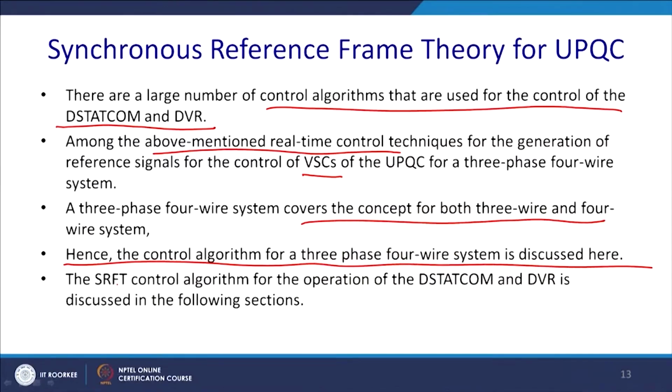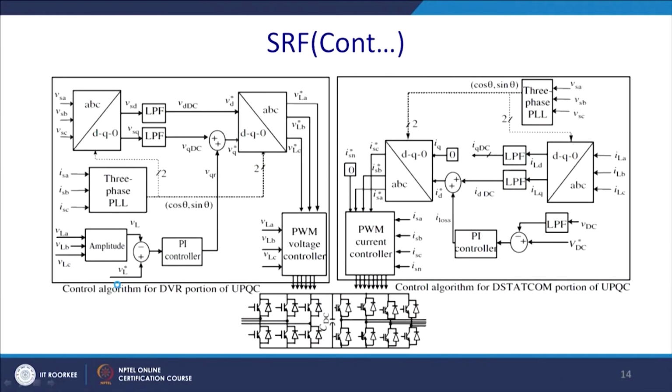So, the SRF theory, that is, the synchronous reference frame theory control algorithm for the operation of the D-STATCOM and DVR, is discussed now. So, this is the overall block diagram of it. Please try to understand. This portion is for the DVR and this portion is for the D-STATCOM.